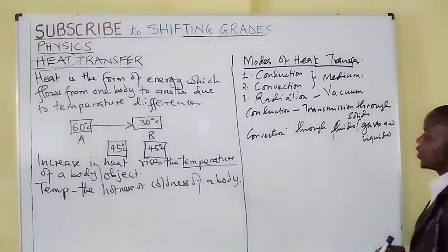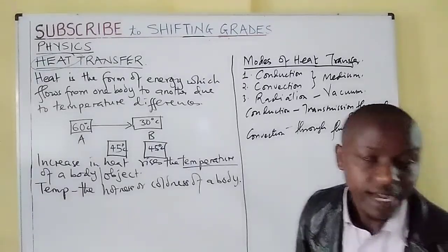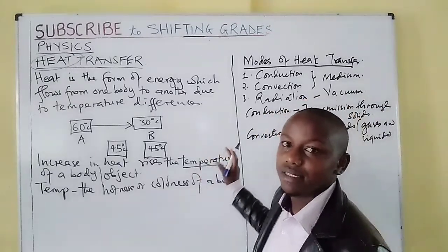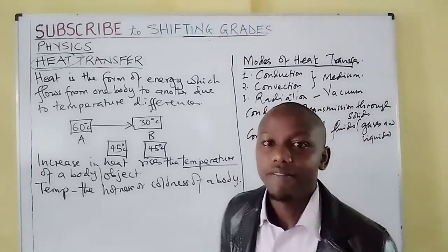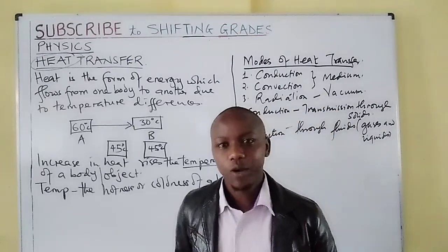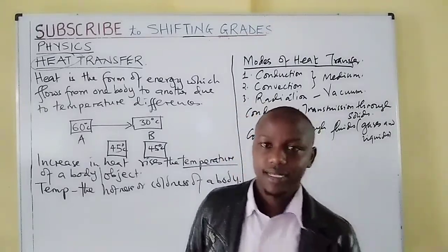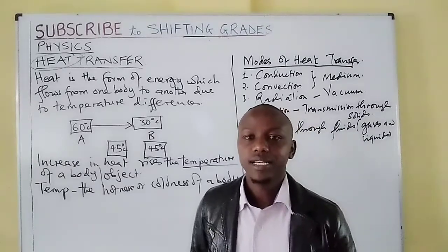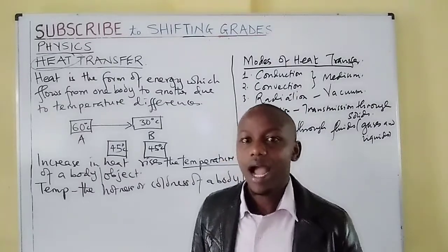So when the word fluid is mentioned, we mean both gases and liquids. Therefore, heat can be transferred by conduction, that is in solids, and by convection, which is in gases and liquids. The other mode of heat transfer is radiation, which takes place in a vacuum.